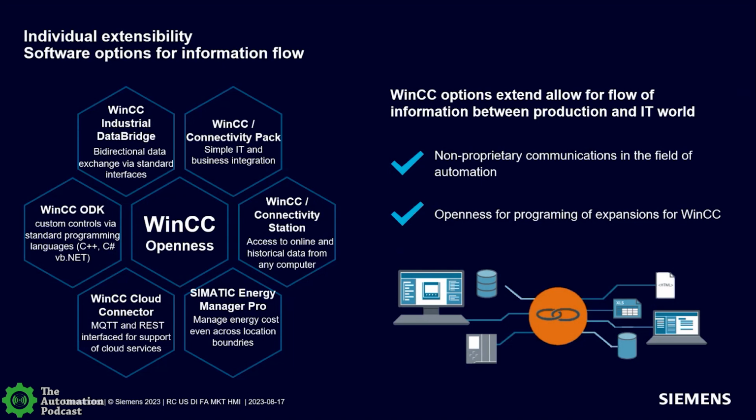If you need to compare one plant to another plant, you could do that. Or if you want to compare lines to lines, see what's going on, just keep an eye on what's going on with the energy usage. So if you see something going out of spec because it's using a lot more energy, you say, hey, maybe there's a problem and I need to do some maintenance on that equipment so that I can reduce some drag and get the motors running better.